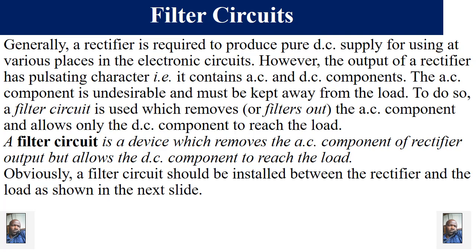So how do we eliminate them? We use a filter. The simple function of the filter is to remove the AC component of the rectifier output, or the ripples, or the pulsations. So where is it installed? It is installed at the output of the rectifier and before the load. It comes in between.